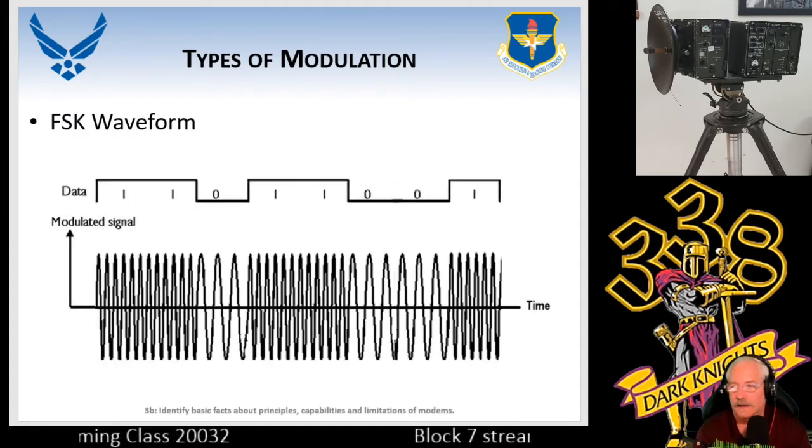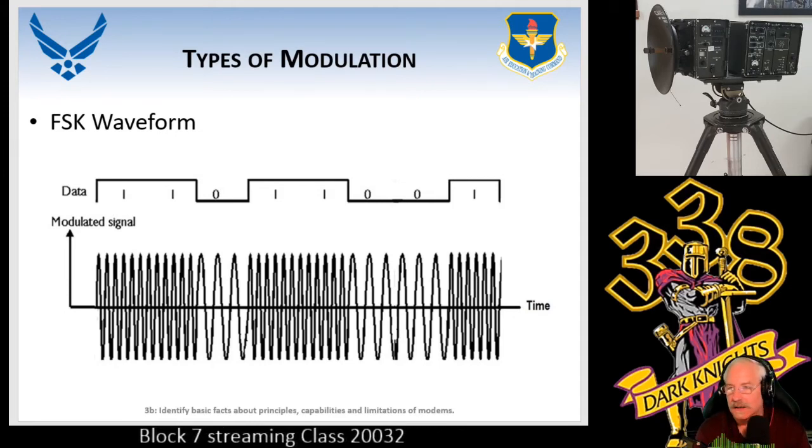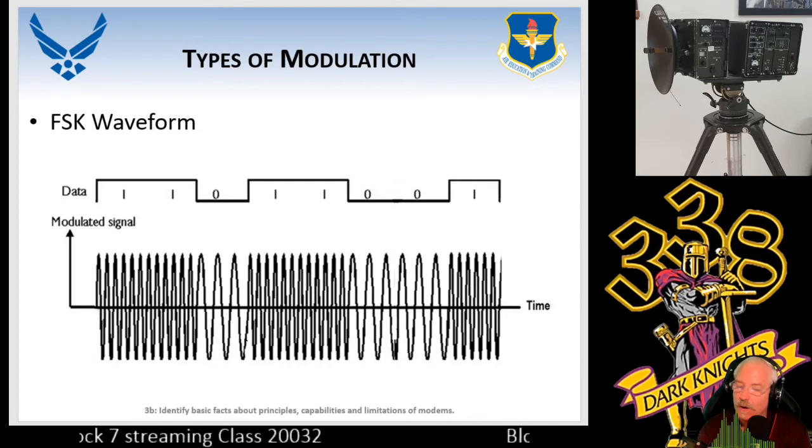Let's look at the waveform with the data. You can see that anytime we have a logic and it continues, nothing happens. It does not change. The moment that it changes from a logic 1 to 0 or a 0 to 1, the frequency changes. You can see that anytime we have a logic of 1, it's a higher frequency. Anytime we have a logic of 0, it's a lower frequency. Pretty self-explanatory.